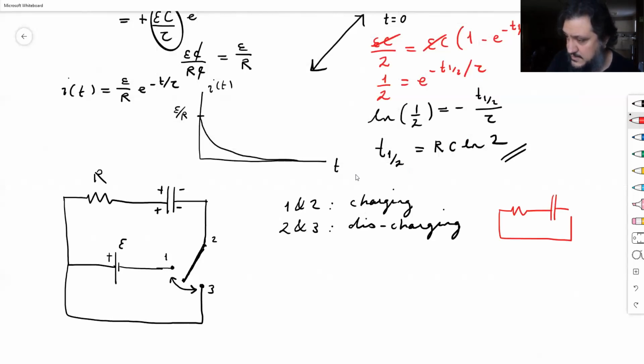Now these two are connected, and I have the positive charges here and the negative charges on the other side. If there will be a current here, and since current is by definition the direction of the motion of the positive charges, I expect a current from right to left on the resistor, whereas in the beginning it was from left to right to charge the capacitor.